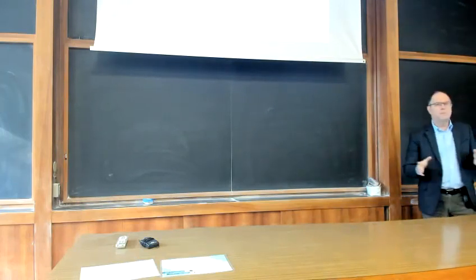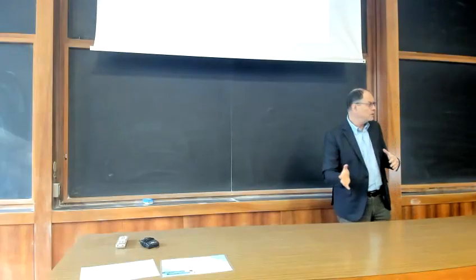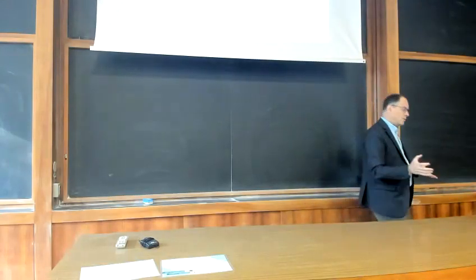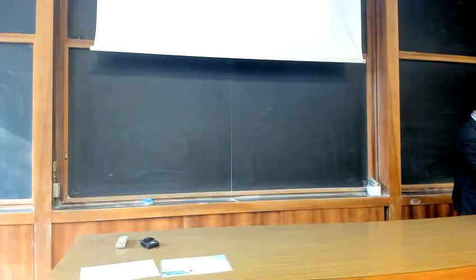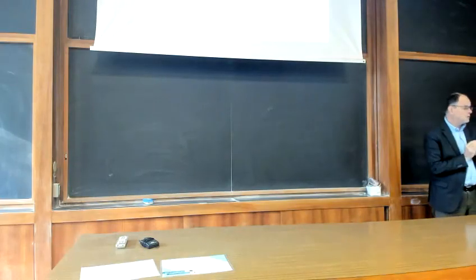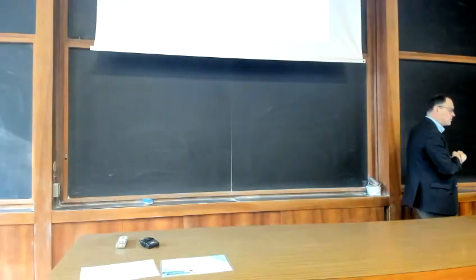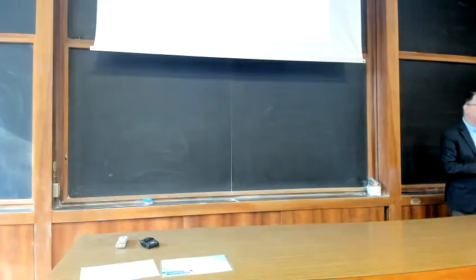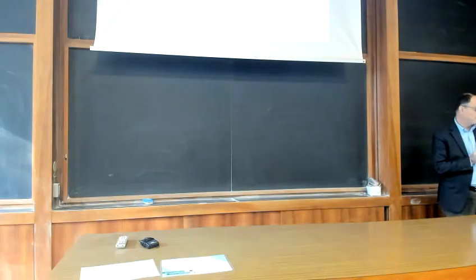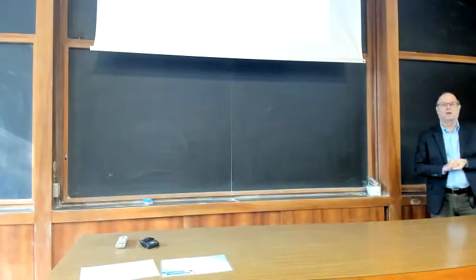Now, in this case, we call it the punching or punching shear failure. And this is valid for loose, coarse-grained soils or compressible fine-grained soils in drained conditions. This mechanism occurs for highly compressible soil under the footing, accompanied by shearing in the vertical direction around the edges of the footing. There is no heaving of the ground surface beside the edges, no tilting of the footing. Relatively large settlements are a characteristic of this failure mode, and the ultimate bearing capacity is not well defined.